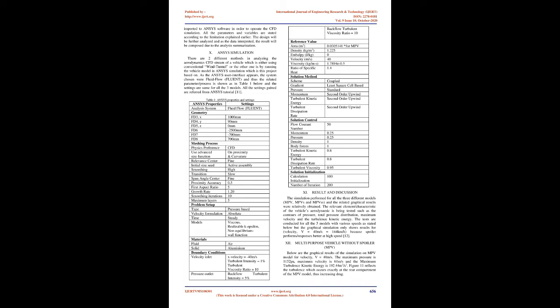Three different types of MPV model need to be built using Catia software: one without spoiler, named MPV; one with spoiler at 90 degree angle with 20 cm length and 8 cm in height, Proton's original OEM specification, named MPVS; and the last with an enlarged spoiler, designed much wider than the original OEM specifications, at 100 degree angle, 50 cm length and 8 cm in height, named MPVSS.